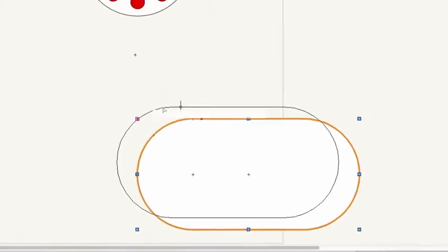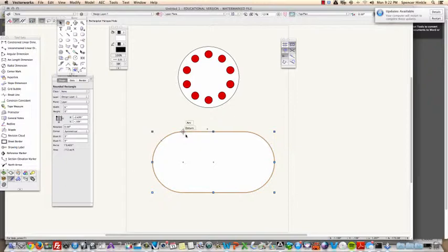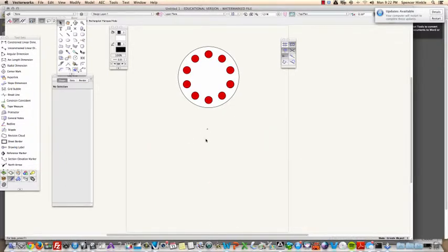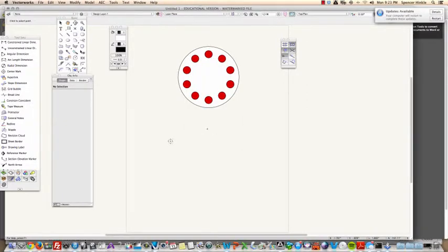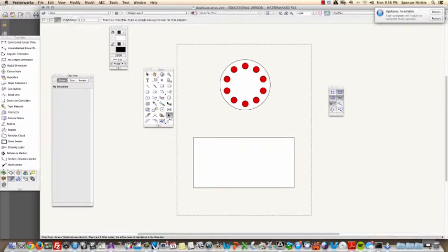All ready for us. Now I should probably show you another option. I could have drawn a regular rectangle that is 6 by 3 and positioned it in here. Here we're going to use the Fillet Tool, which is right here. Fillet Tool will allow us to put a radius on a corner, basically. And its sister tool over here is the chamfer tool, and the chamfer allows us to chamfer or bevel the edge of where 2 lines intersect. They both function just about the same. So let's use the Fillet Tool.